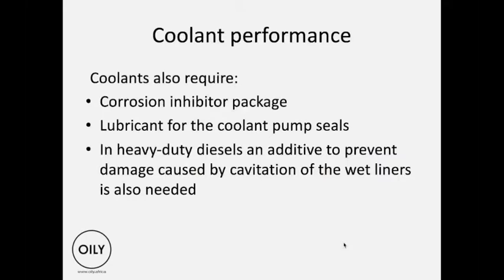So to be used as a coolant, it must have a corrosion inhibitor package in it. It's not just water and glycol. You've got to have a corrosion inhibitor package in it. It's got to be a lubricant for the pump seals and the pump itself. In heavy-duty diesels, an additive to prevent damage caused by cavitation of a liner is also needed.